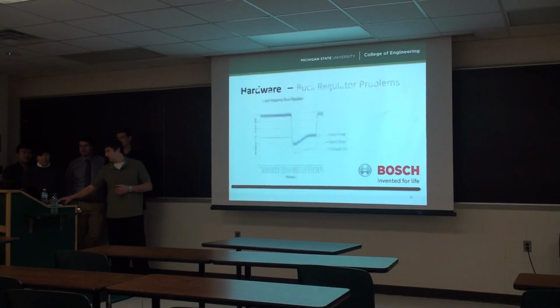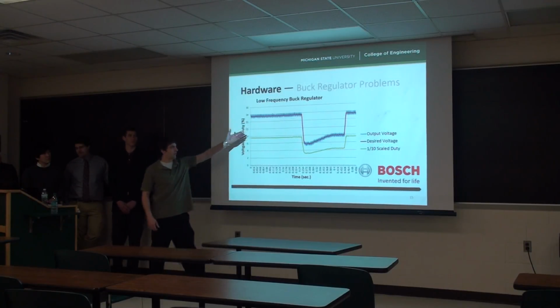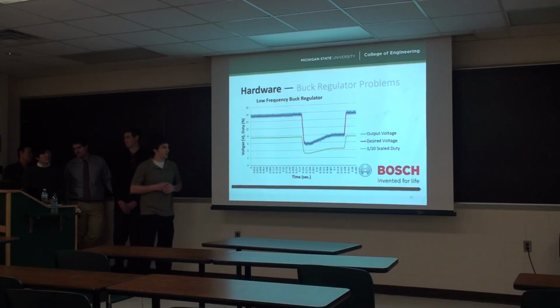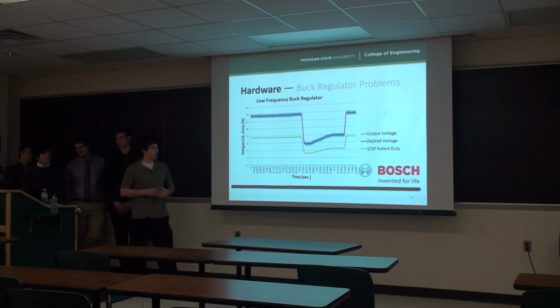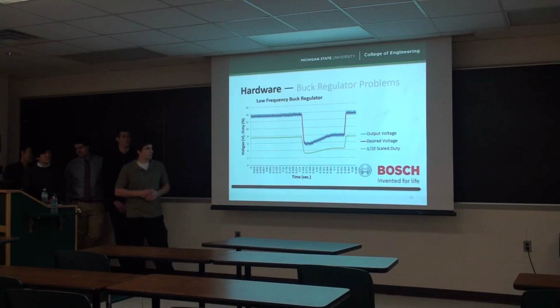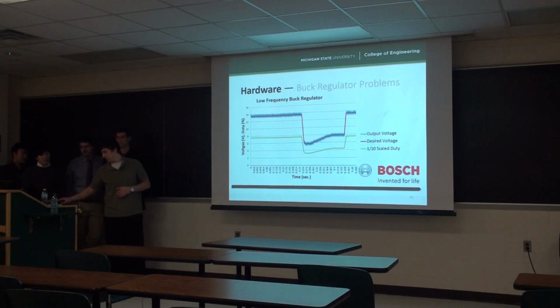So the thing we have to consider is the effect of switching. If we don't switch fast enough, we'll end up seeing these transient ripples, which aren't normally seen from a regular battery. And this also shows the 1/10 scale duty; the simplicity of the control is we just have to vary the duty to follow that, and we'll also use PID control.